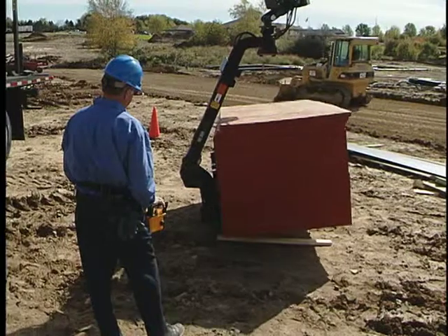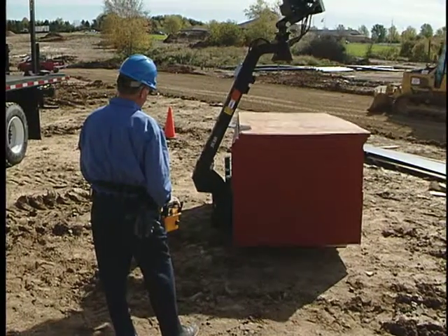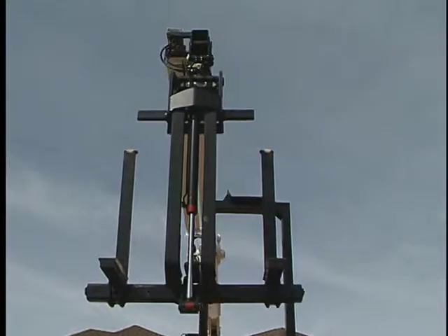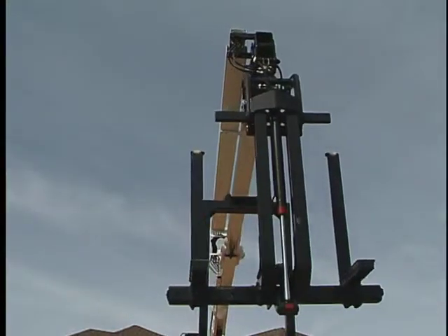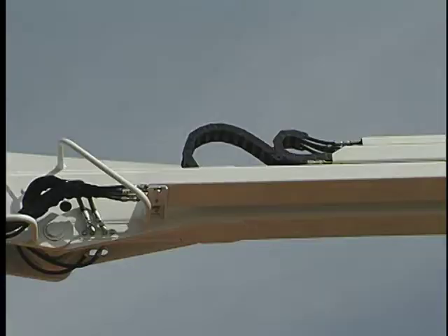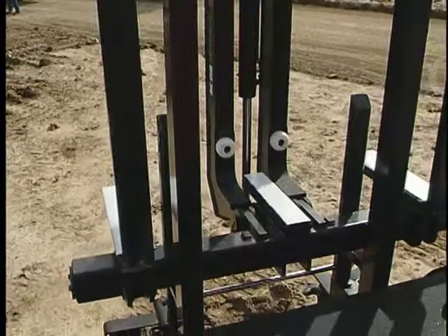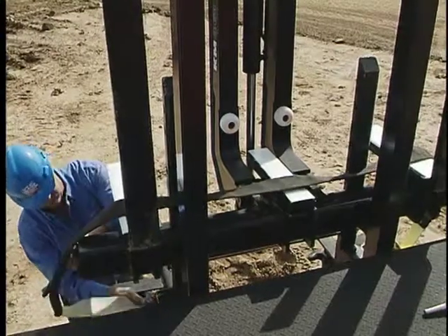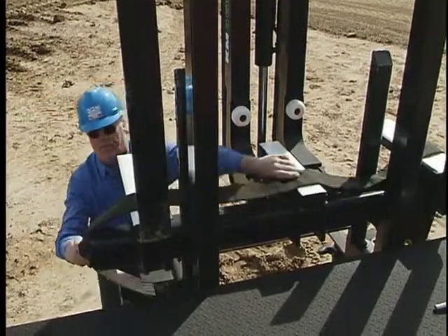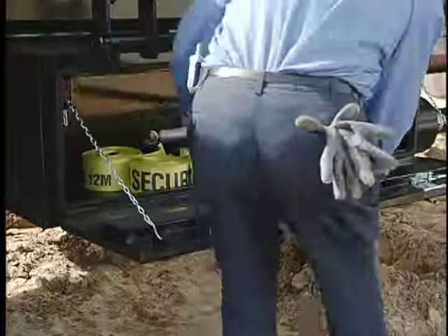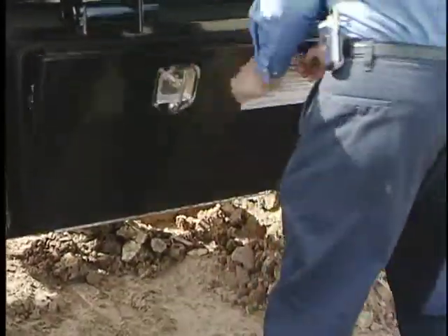Now the truck is offloaded and you're ready to prepare the crane and truck for leaving. Rotate into position beyond the boom rest. Bring the boom extension in. Set the fork back into the cradle. Use the tie-down fork strap. Set the restraining bar in place. Make sure load straps have been rolled in and secured.